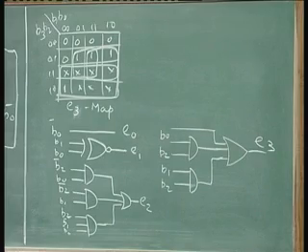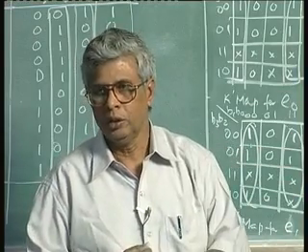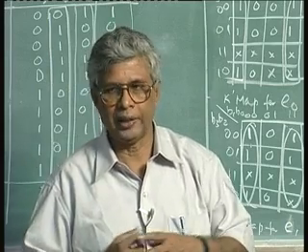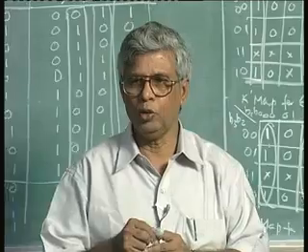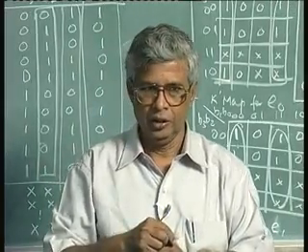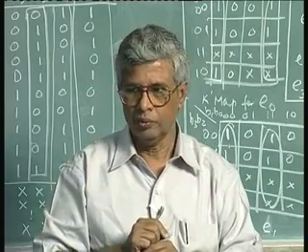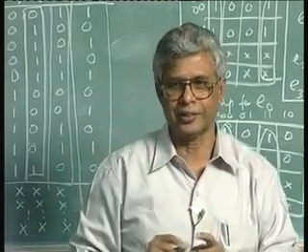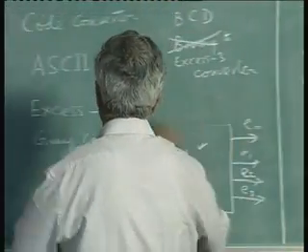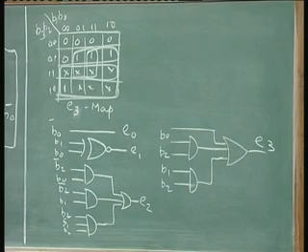From the truth table you get the values for the 4 bits of the gray code using the Boolean reduction technique using K-maps, then draw the logic. So, I will give you the table and the result. You have to draw the circuit and verify my results are correct. If the results are wrong, that means you have done something wrong because I am going to give you correct results, okay. So, let us talk about the gray code converter, binary to gray. Now, this time I will do binary to gray code, not BCD.